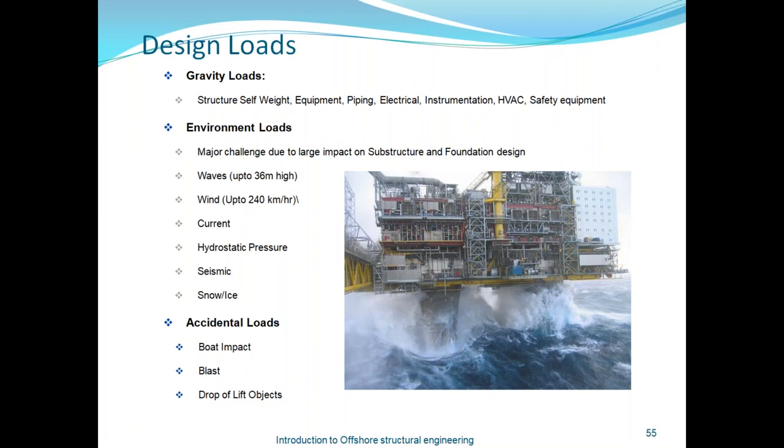We generally have these loads in offshore structures: gravity loads. That means structural self-weight itself. We have equipment, piping, electrical, instrumentation, HVAC, safety. These are all gravity loads. That means whatever loads we generally apply on the structure, or are generally existing on the structure.